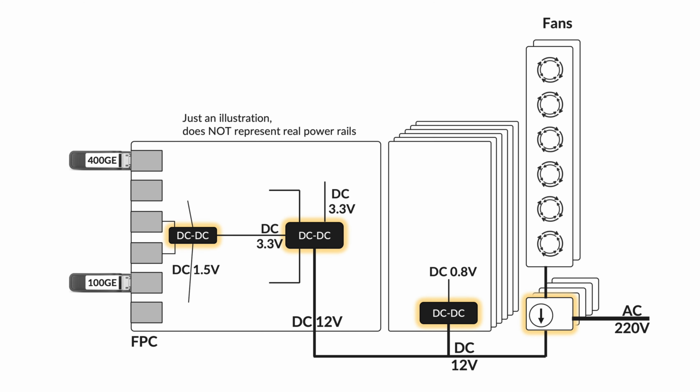Also, it's important to know that voltage conversion is done in multiple parts inside the boards. We have POLs, point of load converters, that will convert it to lower voltage current to feed different components. Some parts will need 0.8, 1.5, 3.5 volts, etc. Here again we have a conversion efficiency, and that's also valid for the optic modules.